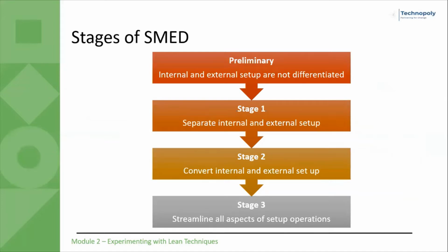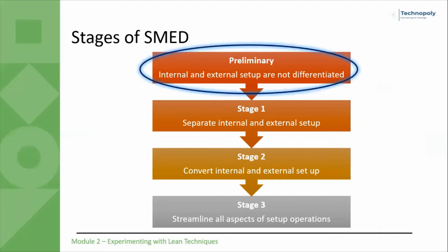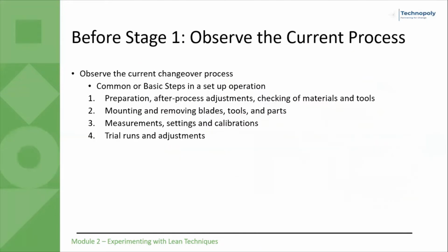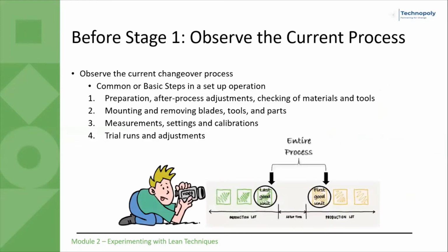The first step of SMED is to establish all elements of the setup operation. This is done during the preliminary stage. In the preliminary stage, we observe the current process of changeover. Some of the common or basic steps in a setup operation are listed in here. We need to record each step in the process by sequence and the time taken.